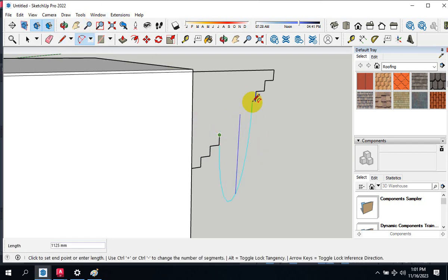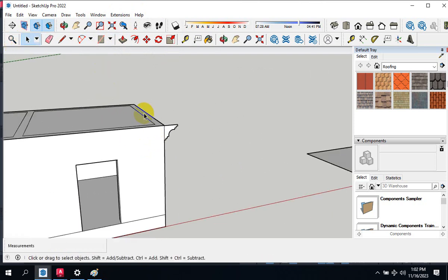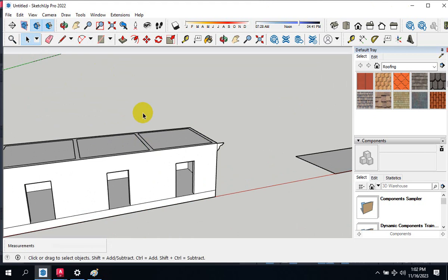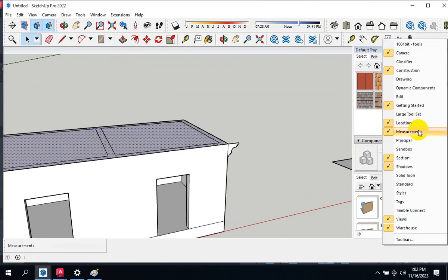Then I'll introduce the tool. So, clicking up here, there is a tool that is called Follow Me. Although it is a common tool, it is behind here. But we know how to bring it back. We'll come here and right click.